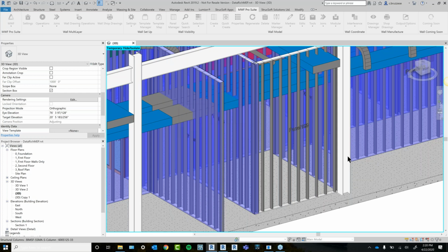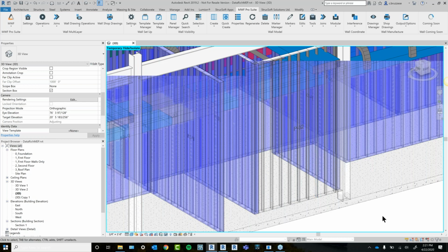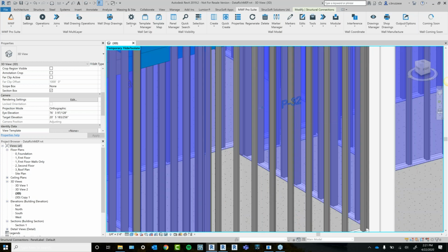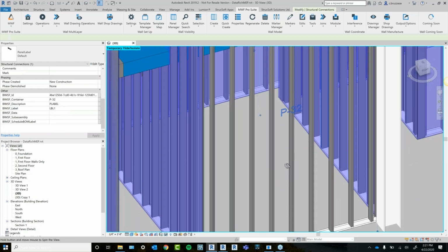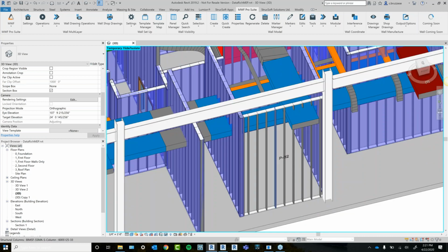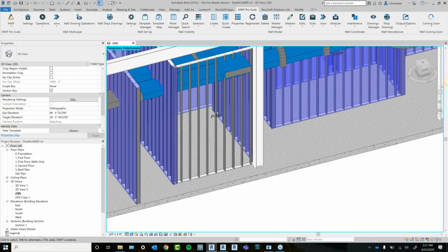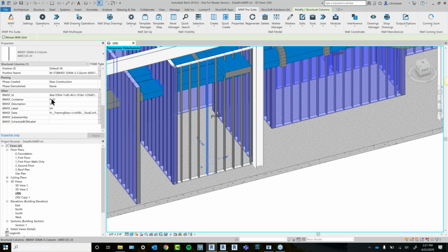And then it's just going to run through my project, and it'll rename all my panels and use that position ID. So it is a nice little tool if you want to group your panels together under one ID. It renames the panel with that position ID. So you could always pull that into a Revit schedule if you wanted to as well.